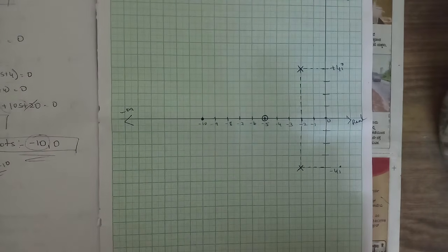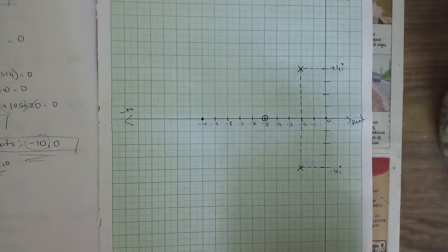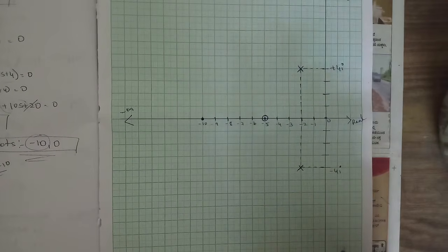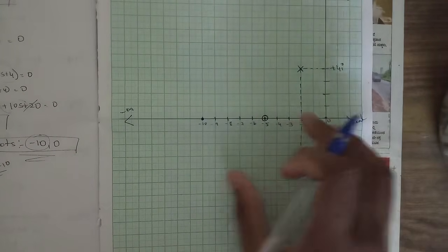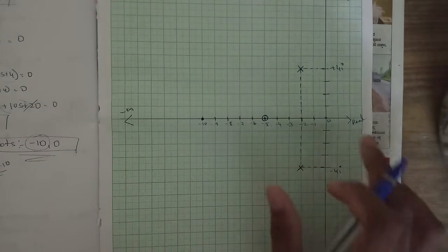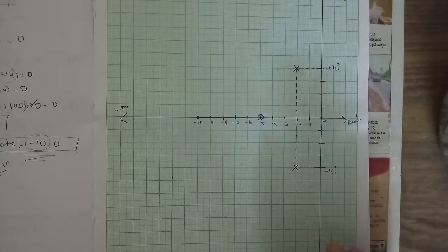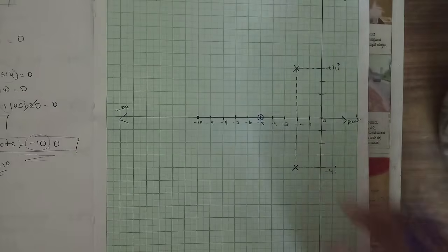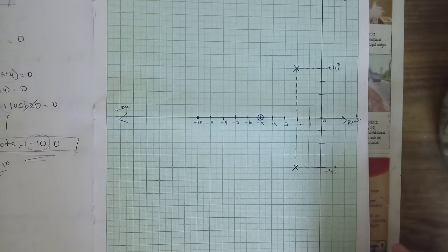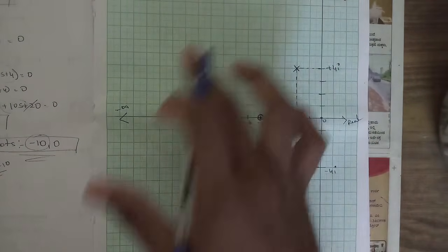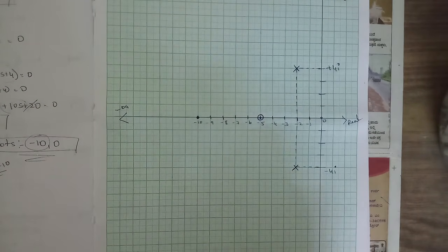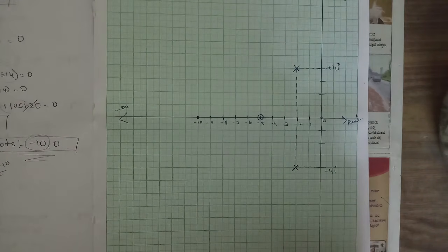Now there is the task of finding the root locus, and for that, since the poles are on the S plane, not symmetric with the real axis, it is on the surface, it's not on the real axis or the imaginary axis. But in order to see in which direction the branches are moving, in case of the complex poles, we need to be finding the angle of departure.